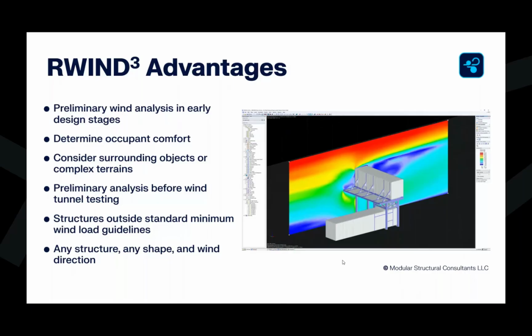Now, if your project does require a true wind tunnel test, and there's no way around that, this tool can also be used. You can put your structure into this numerical wind tunnel and adjust the design before spending the time and the money to carry out the true wind tunnel test, to determine that our design is not adequate. So being able to make those modifications, again, very early on.